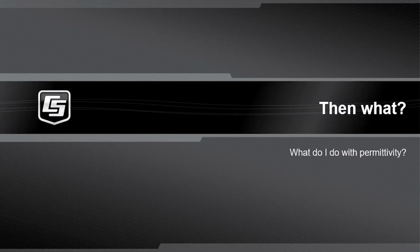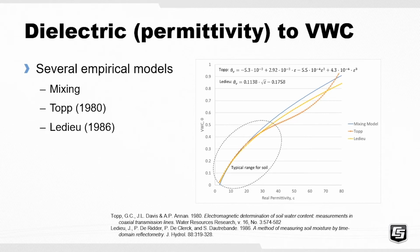So then you might quite reasonably ask, what do I do with permittivity, or the dielectric constant? There are a variety of empirical models to go from dielectric to VWC, and the most common amongst those are the Topp and Ledieu models. Over here on the top of this graph, you see the two equations, and the references are there at the bottom for your information.